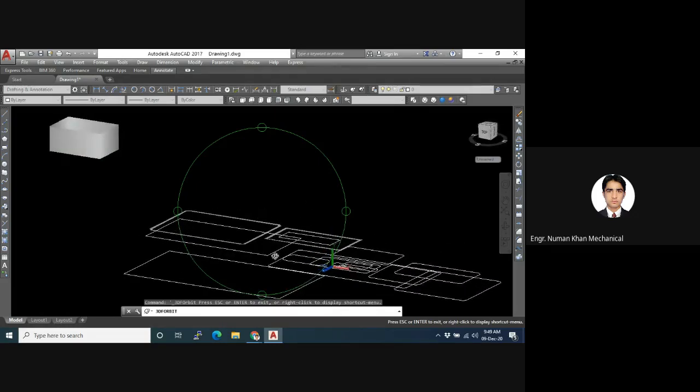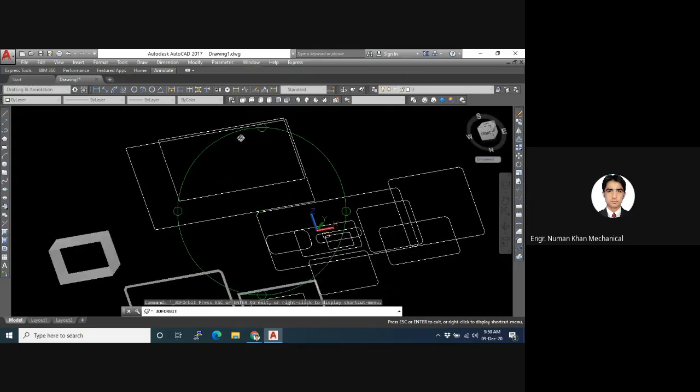So such types of commands are used when we are converting 2D into 3D, or when we are drawing different types of objects to be converted into 3D using the loft command. Loft is a command in 3D with the help of which we can join the cross sections located at different elevations to be converted into 3D. Okay, so we can do that when we study 3D, God willing. But you should keep in mind the meaning of elevation and thickness in this rectangle command.